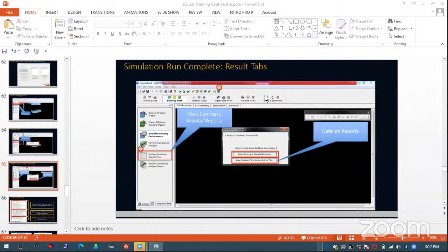No, auto size means you want the software to do the calculation and let you know what will be the total tonnage and what will be the total CFM. We are having a duct. In our yesterday's presentation, you might have seen that in a package AC, there will be a duct. And duct may have many elbows and many bends. And based on the elbows and bends, you may have static pressure. So what can be done is, if you have your shop drawing ready, you can do ESP calculation. ESP stands for external static pressure calculation.